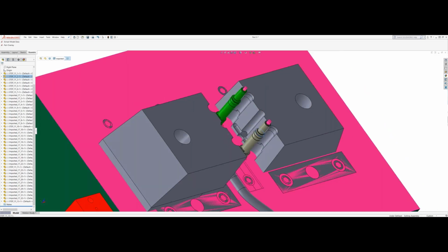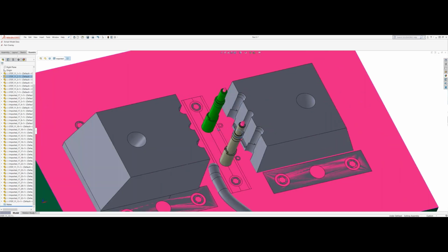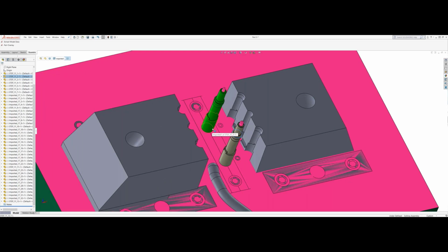In this case, we only had one point gate right here on the side. Imagine as pressure hits this core pin inside, it's going to want to push it towards the other side. Where if you have a gate on two sides, you get even pressures pushing on both sides, canceling it out. So we had to lock this pin into the cavity side to keep it straight.